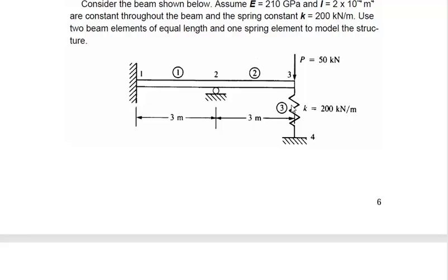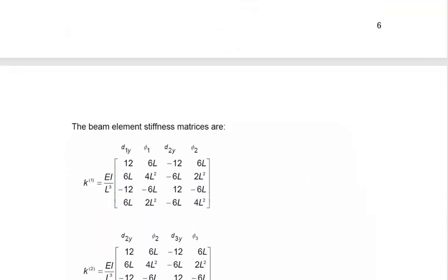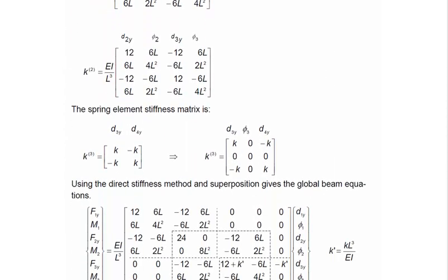So in order to adjust the element stiffness matrices so that they are compatible and they can be assembled together, in the element stiffness matrix of a spring element, we will have to introduce another degree of freedom which corresponds to phi 3. And we know that there would be no rotation from this side. So the corresponding rows and columns would be 0, right?